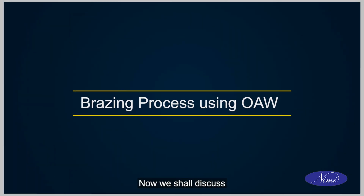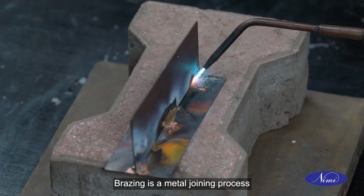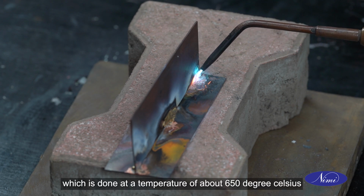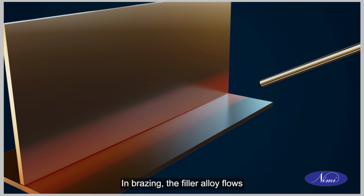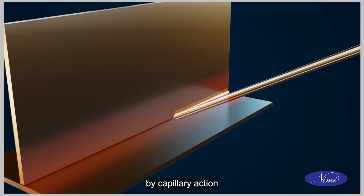Now, we shall discuss the brazing process to get T-joint on copper to MS sheet. Brazing is a metal joining process which is done at a temperature of about 650 degrees Celsius. In brazing, the filler alloy flows between two closely adjacent surfaces by capillary action.